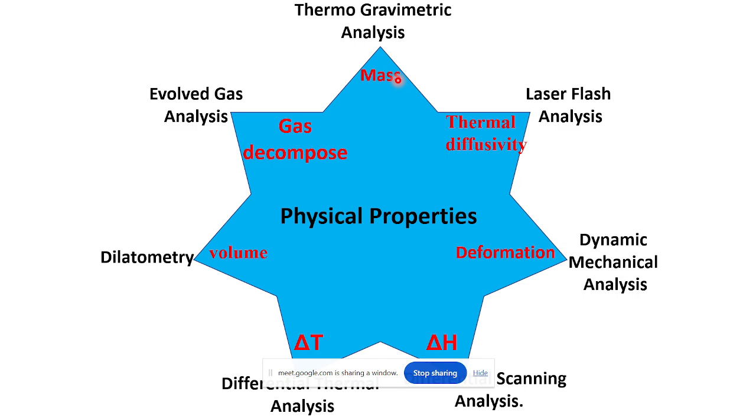So from the thermogram, you will see different steps of weight reduction. From that, you may predict what are the different elements present in the composite material. And also, to prove the thermal stability of your material, you will get knowledge from the TGA analysis. So we are scanning temperature and we are measuring the loss of mass with temperature.